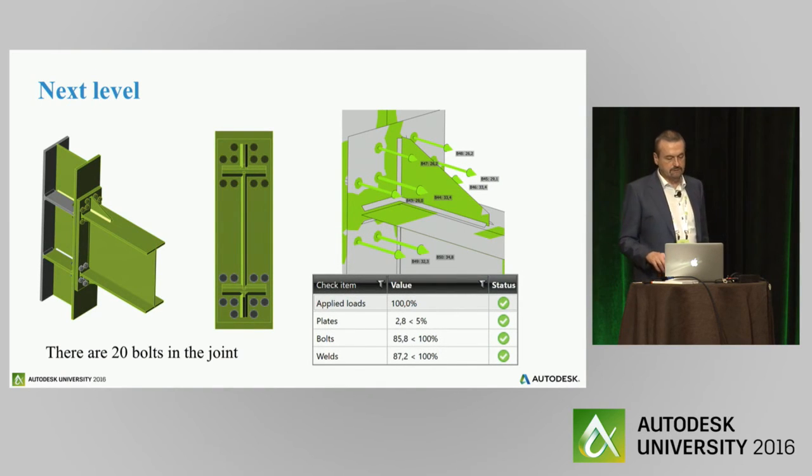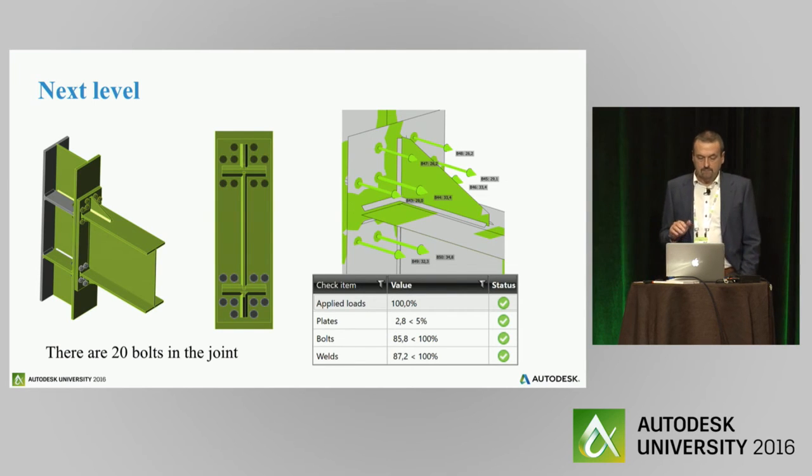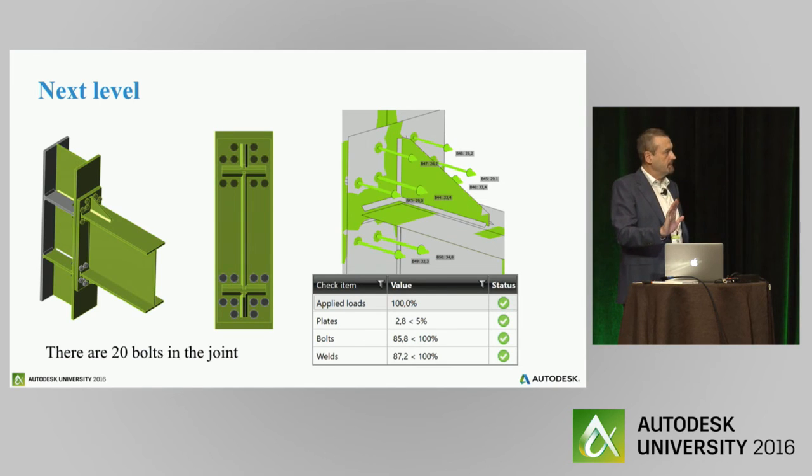in optimization, and we tried to get rid of also the bolts in the second row below the flange. And again, now we have only 20 bolts, and the design is still satisfactory. Only you see in the forces in bolts that now almost all bolts are loaded with the same force.